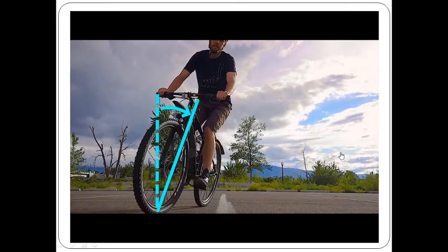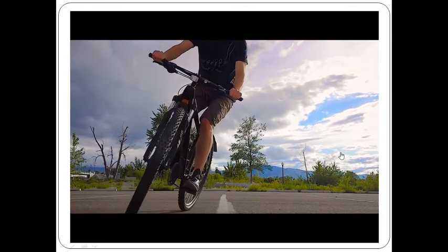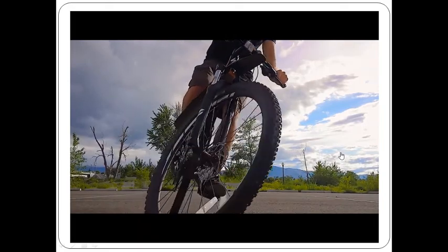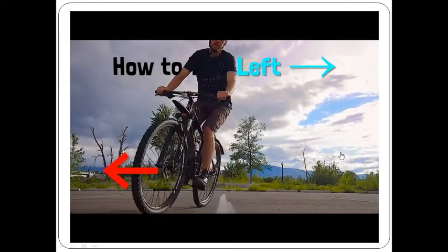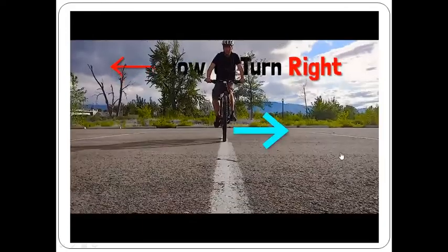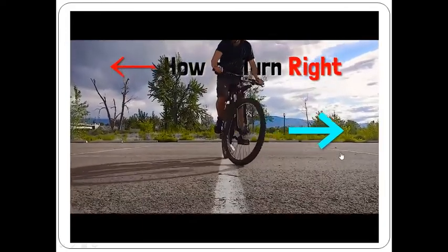So now you're leaning to the left, and the force on the bike from the ground will be directed to the left, and a leftward force, of course, makes you go to the left. Since physics seems determined that you're going to the left, you'd probably better just give in and let the handlebars turn to the left too. And that's how you turn left on a bike, by first turning right. If you really wanted to go right, you should have started by counter-steering to the left.